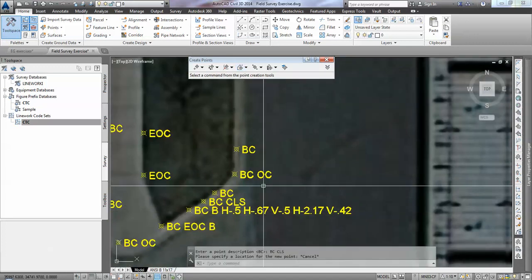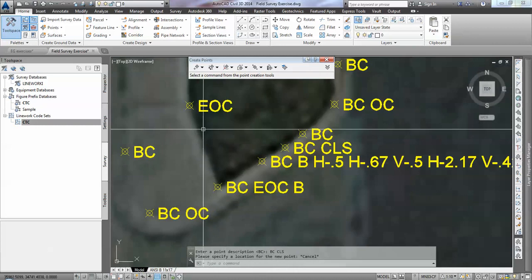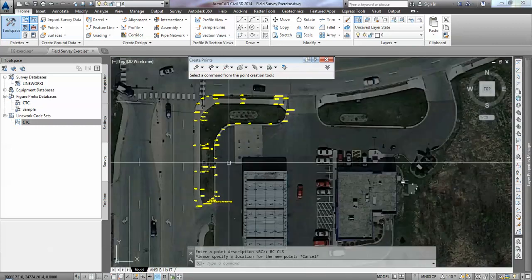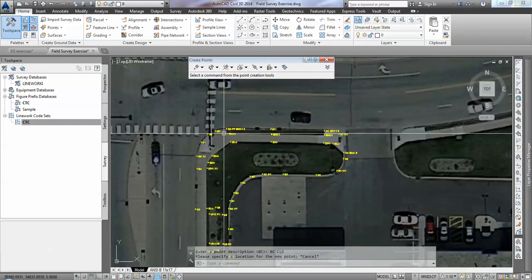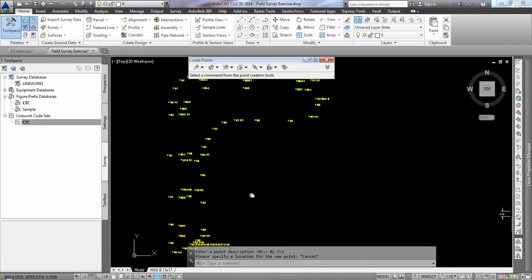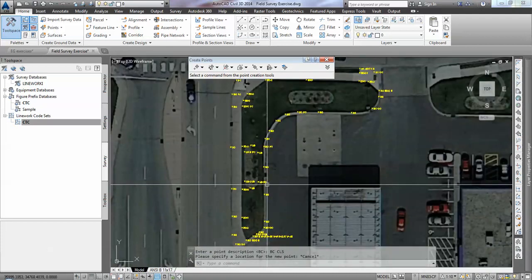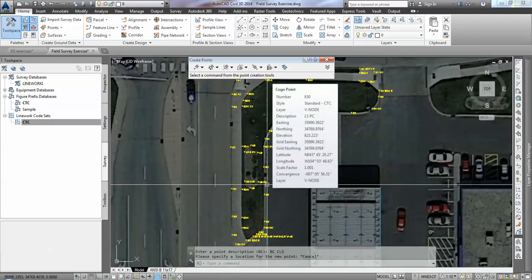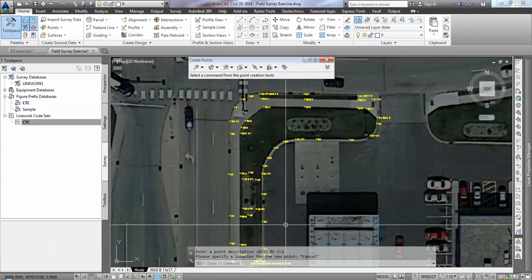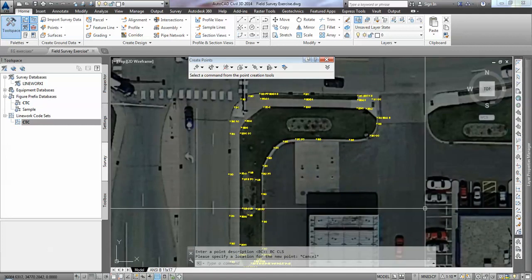Okay, that's a way you can utilize horizontal and vertical offsets. I use the OC command. I shot multiple survey figures from the same survey point. A lot of different examples there. When you get used to surveying for automatic line work, at the beginning you have to kind of analyze the site. Think about how you're going to walk the site.